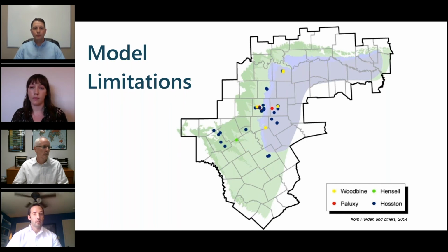One of the more important boundaries in a model is, of course, the recharge applied to the top boundary in the model. Traditionally, this has been done a number of ways, but newer codes have improved on what we've done before. An example of that is the soil water balance code to produce spatially distributed estimates of recharge, applied through the recharge package.